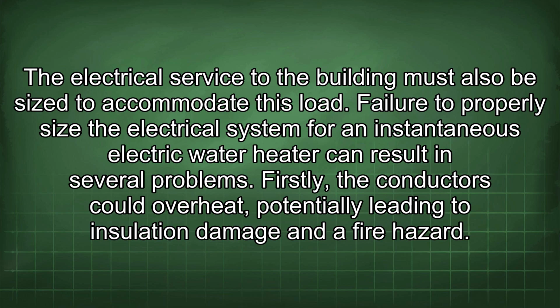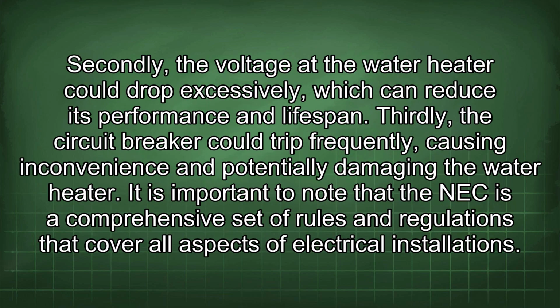Failure to properly size the electrical system for an instantaneous electric water heater can result in several problems. Firstly, the conductors could overheat, potentially leading to insulation damage and a fire hazard. Secondly, the voltage at the water heater could drop excessively, which can reduce its performance and lifespan. Thirdly, the circuit breaker could trip frequently, causing inconvenience and potentially damaging the water heater.